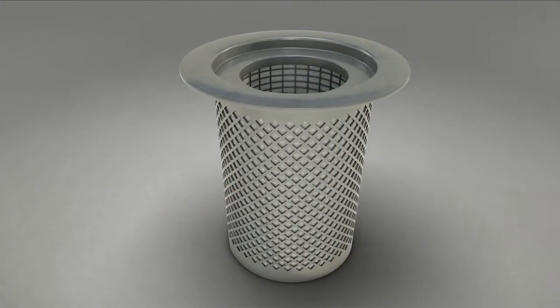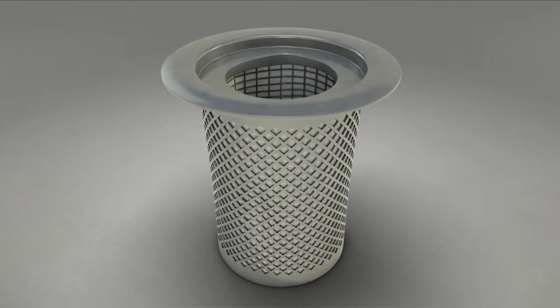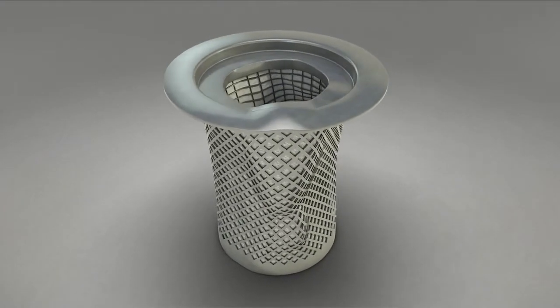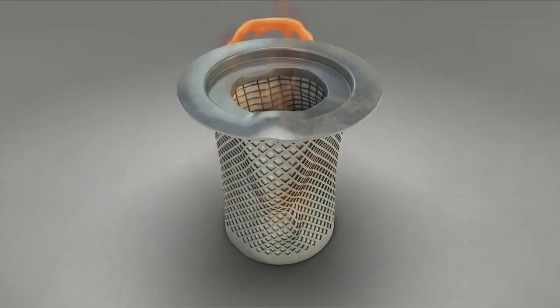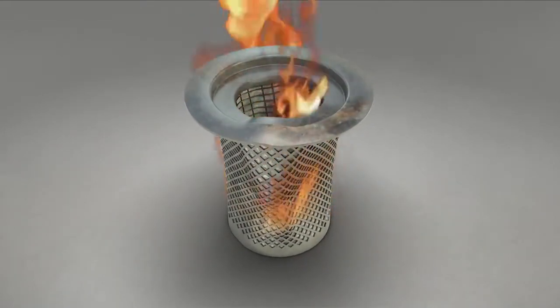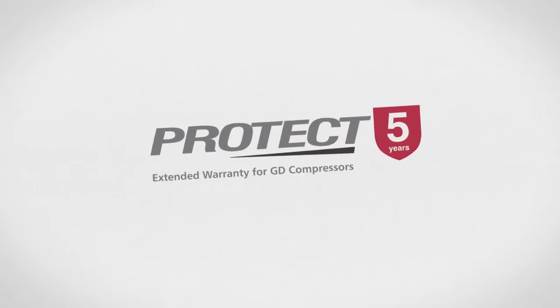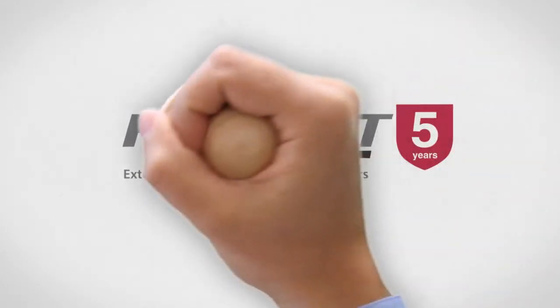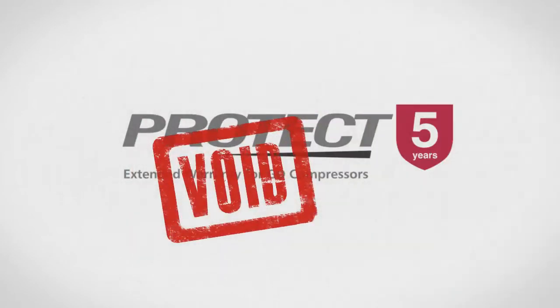In addition, there's the risk of a complete collapse of the air-oil separator due to increased pressure differential, or, if the element isn't suitably earthed, a fire caused by static discharge. And don't forget, if something does go wrong, you're effectively on your own. Using non-genuine parts voids your warranty.